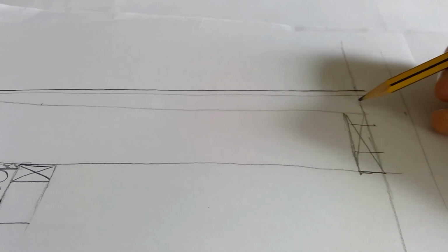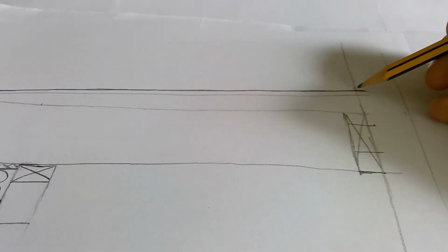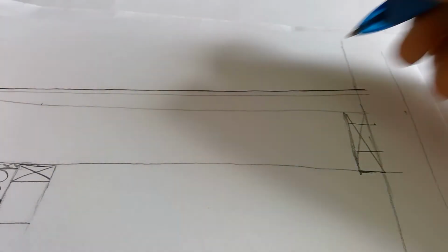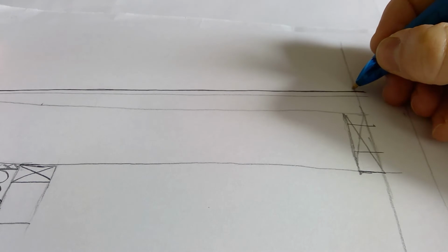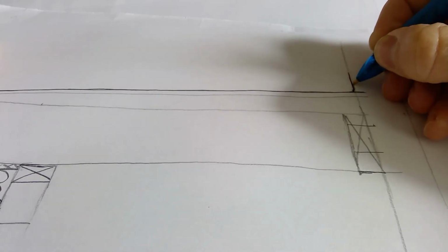The fairing piece runs all the way to the end, your plywood runs all the way to the end, and your bituminous felt runs all the way to the end. That felt, to help prevent the ingress of water, which is mentioned, runs up the side of the wall like that.